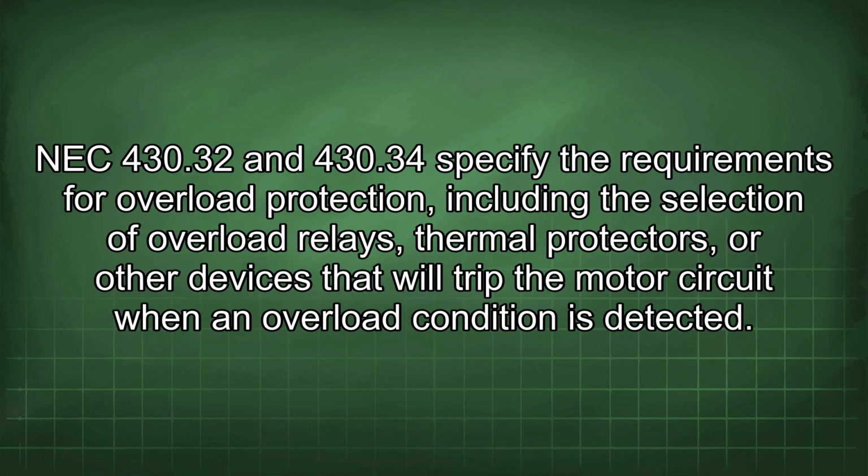NEC 430.32 and 430.34 specify the requirements for overload protection, including the selection of overload relays, thermal protectors, or other devices that will trip the motor circuit when an overload condition is detected.